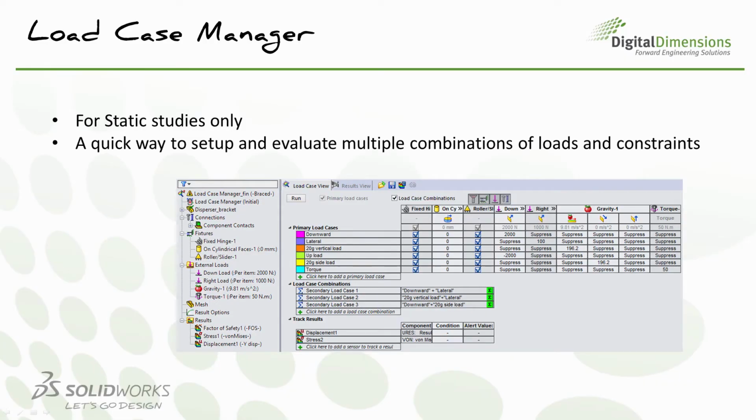The next capability we're going to be talking about is called the Load Case Manager. Now, as you can see here, this functionality is currently only being used in static studies. Hopefully in future releases we'll be able to see this functionality in other study types. But the idea behind this is similar to design studies, where you can take combinations of constraints, whether it be fixtures or displacements, loads, and combine them in different combinations and get some results.